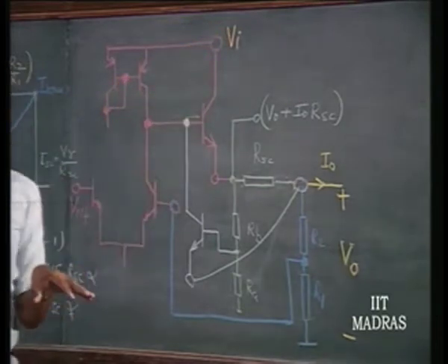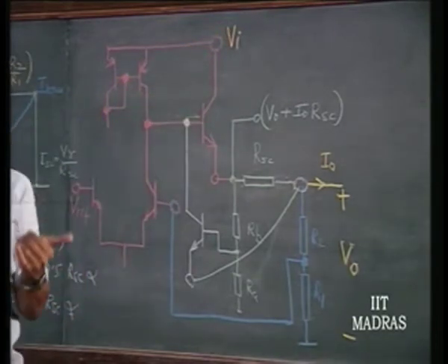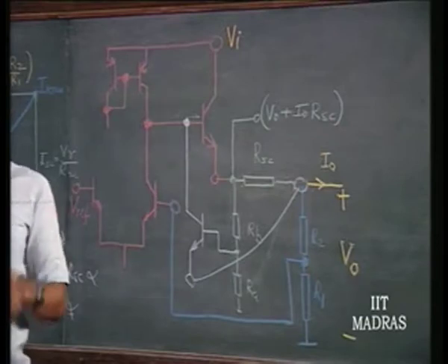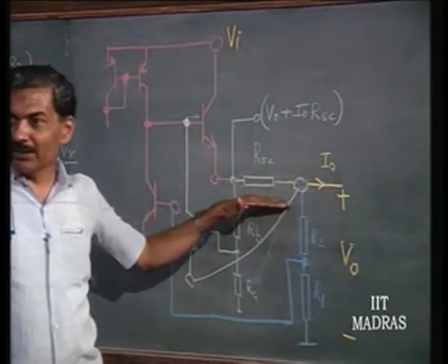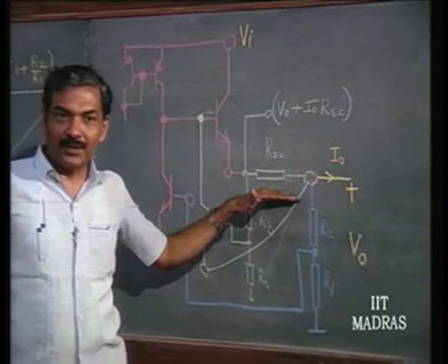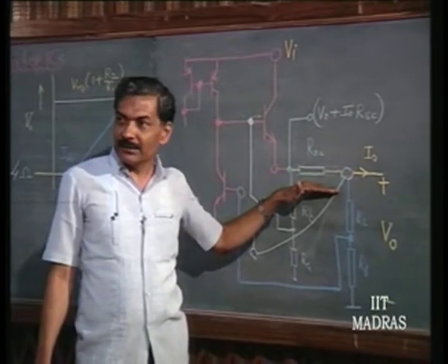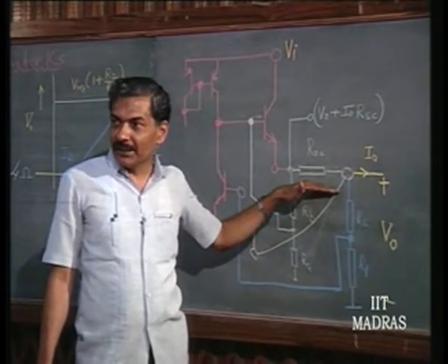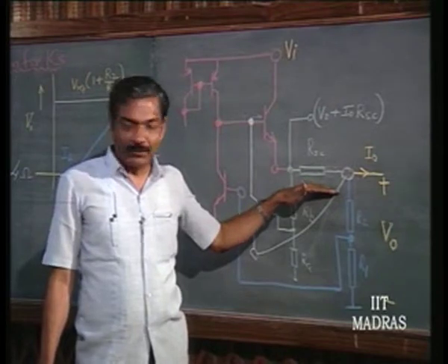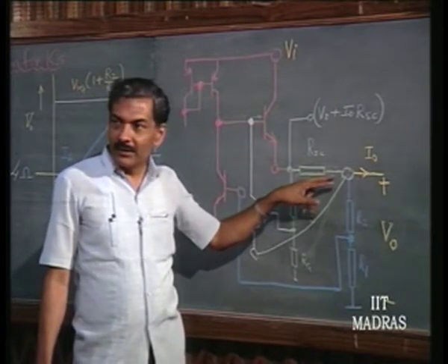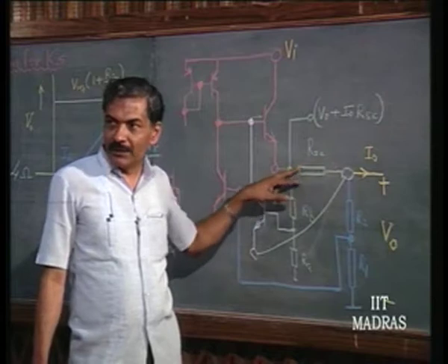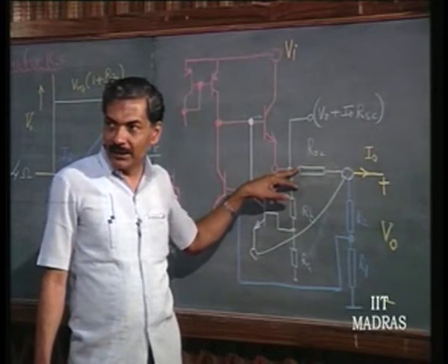Apart from this, the output impedance, as he points out, is invariably going to be affected. Again these are all things which are going to be spoiled for our normal functioning, just in order to take care of short circuit protection. The output impedance, without feedback, is going to be involving RSC straight away.